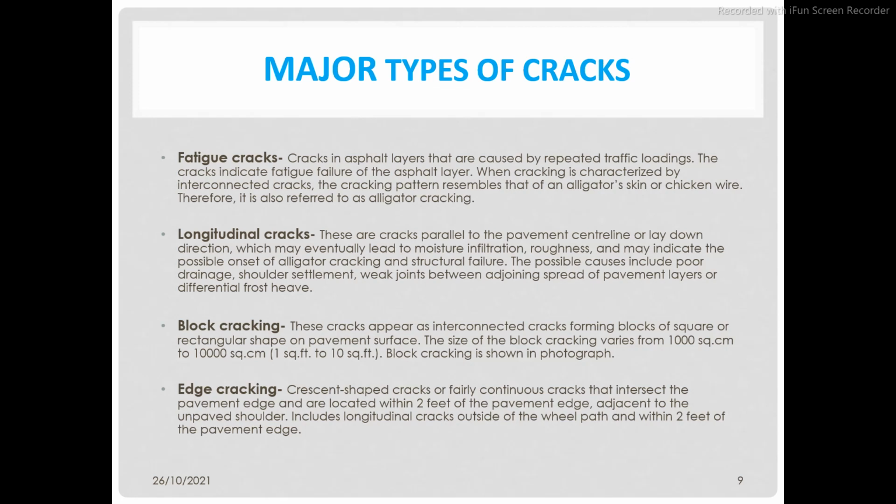The possible treatment depends on whether the pavement is structurally sound or unsound. Where the pavement is structurally sound, the crack should be filled with low viscosity binder or slurry seal or fog seal depending on the width of the cracks. On some cracks, pavements would need strengthening or rehabilitation treatment.